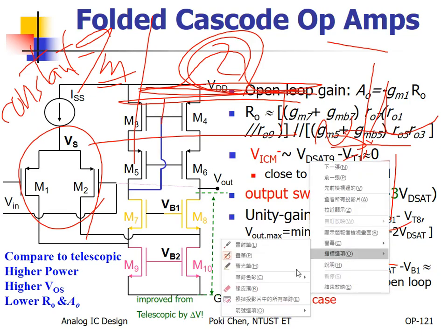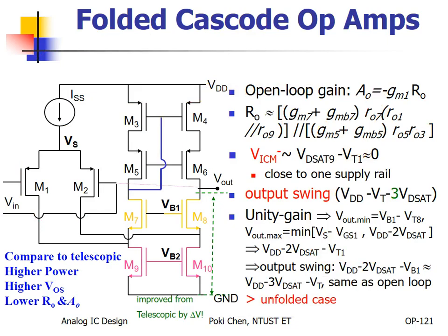It means, in practice, it cannot function in this way, with a clear cut in the middle. No. If the voltage here has some kind of noise, your circuit will switch to the left, switch to the right. It will cause a lot of switching noise. So for switching, you need hysteresis, 迟滞.